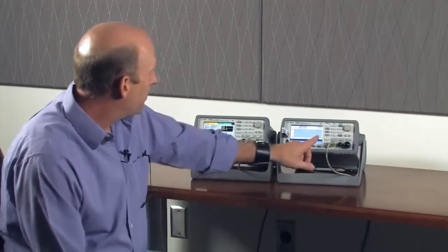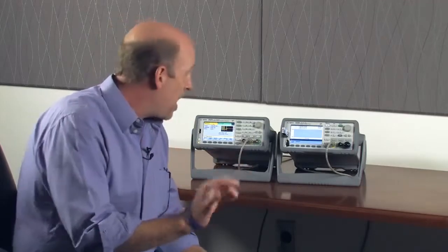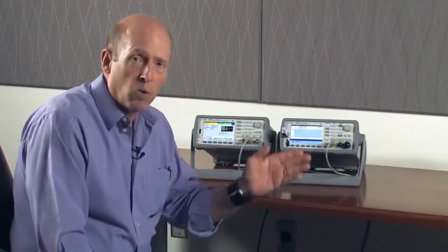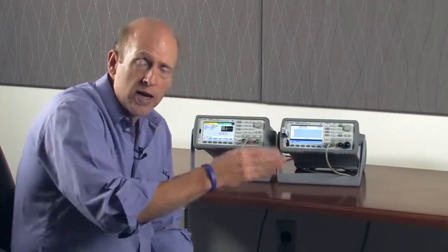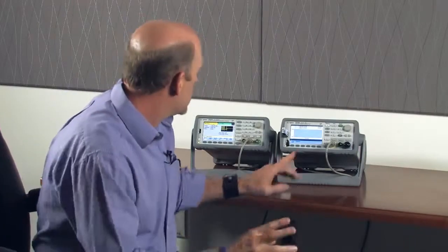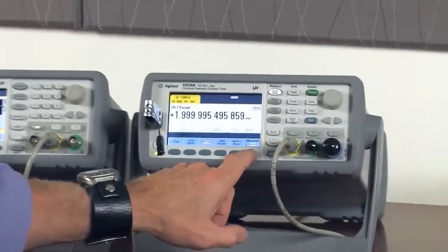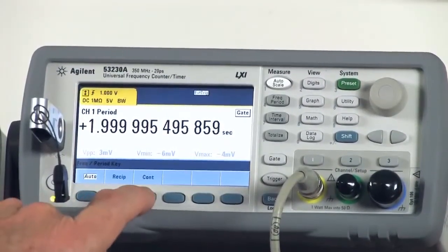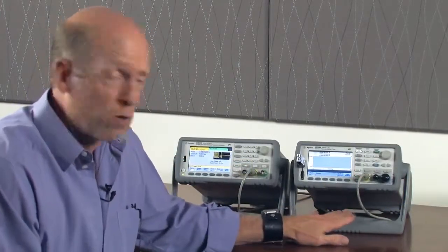As a result, we've only been able to take within auto mode 2 measurements of the 10 cycles that were coming in. To alleviate that, we switch to continuous mode, where, as I had described it before, we have one gate open and one gate closed sequence, and all of our readings are taken in succession in the middle. So to show that, I will go back and change the reading mode from auto to continuous.